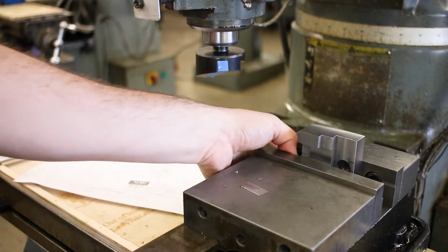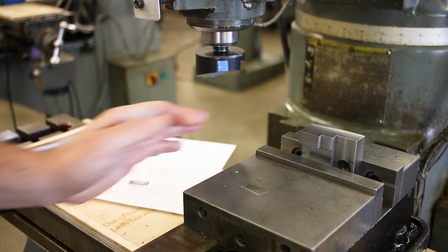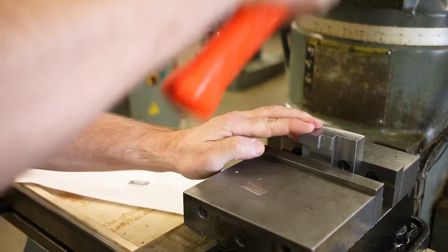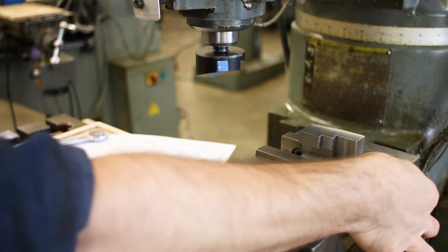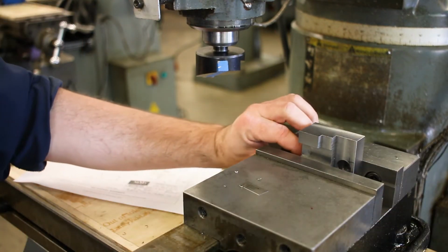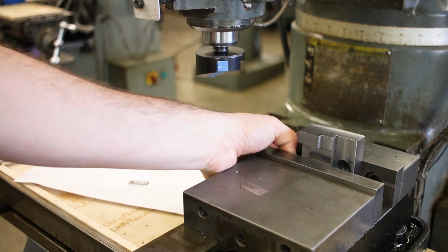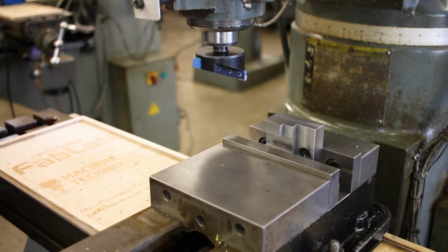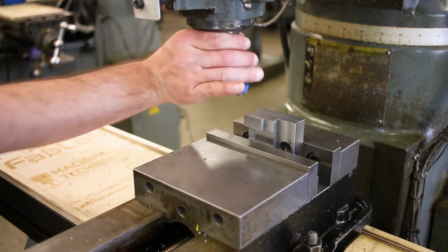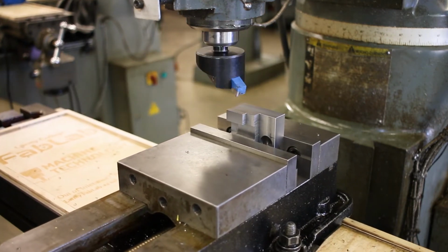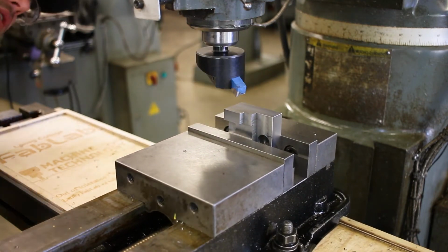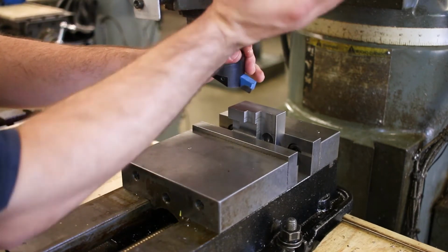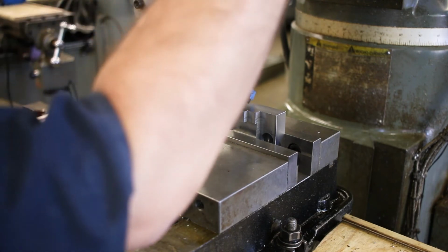That shim doesn't move. That shim doesn't move. Does this shim move? Yes, it does. Give it a little tap right here. Doesn't move. Doesn't move. Doesn't move. We're good. All right, folks, you know the tune. Let's do it again. Go ahead and position this to the center of the part, going this way. Bring it a little bit closer with the quill.